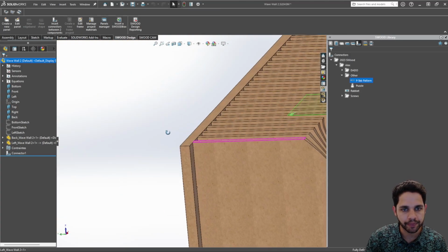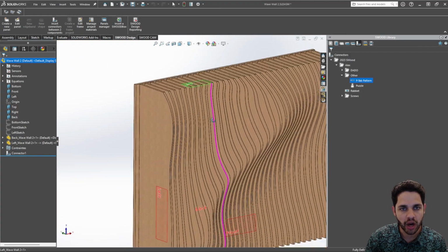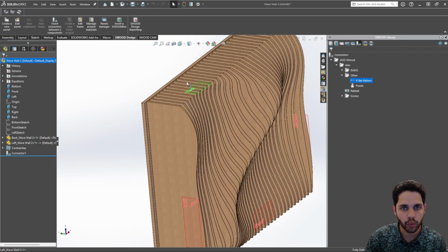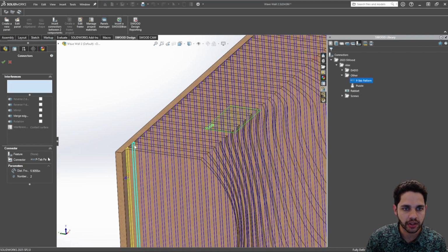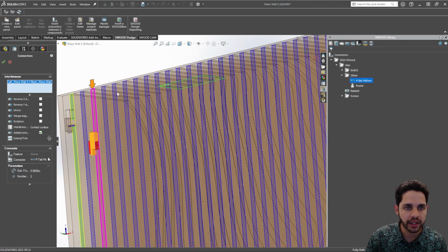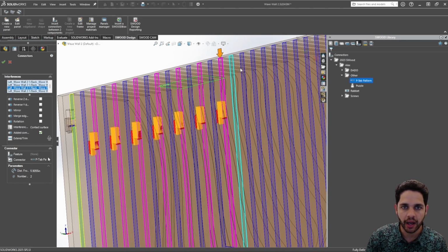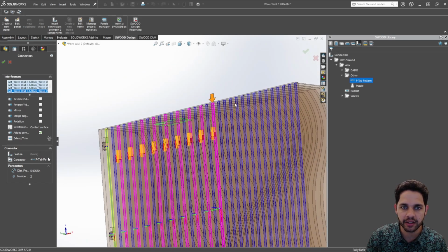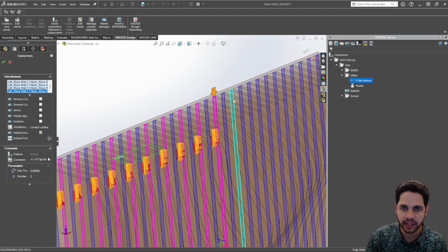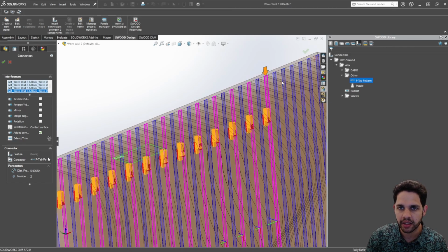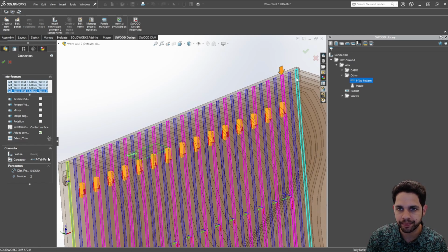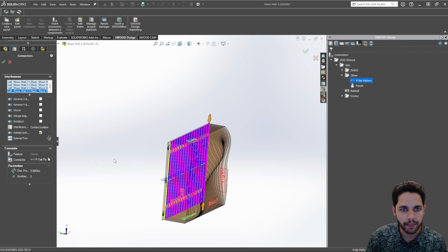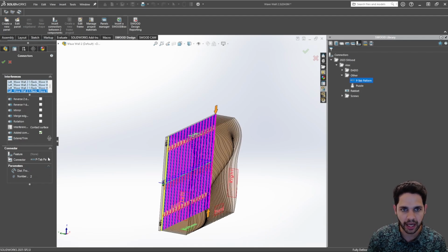Now I can come through and drop in that connector for each one of these instances. So I'll go ahead and do that. I'll insert connectors. We're going to do every other connector first, because I want to create an offset that's just better for cutting on the CNC. I'll show you guys what I mean. So I'm going through, selecting every other panel, and we're going to make this one 3 inches from the top.